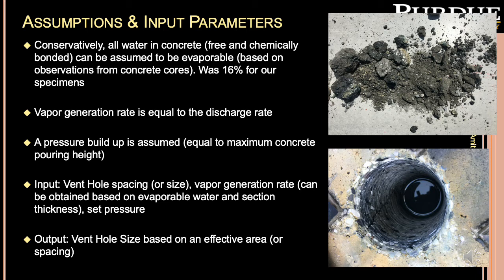The first assumption that we made was that all of the water in concrete, be it the free water or the chemically bonded water, is evaporable. And for our specimens, that water percentage was 16%. This assumption is primarily based on what we had observed from our specimens.